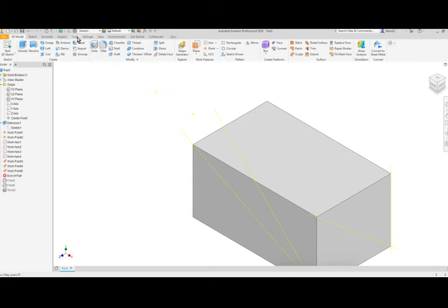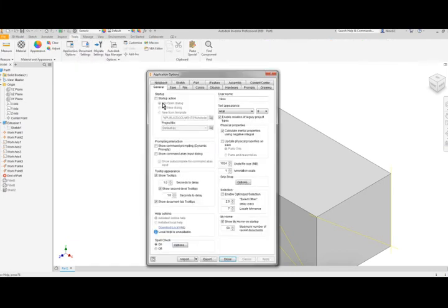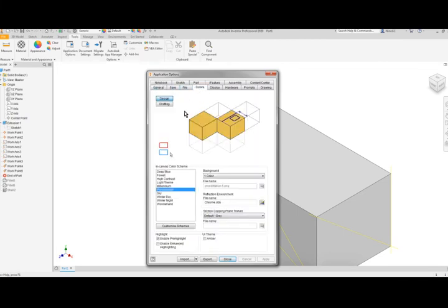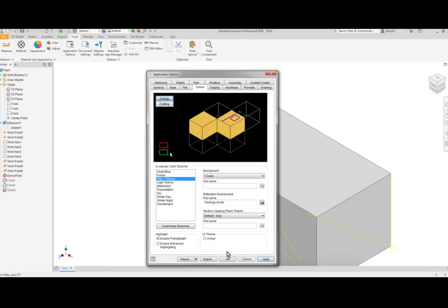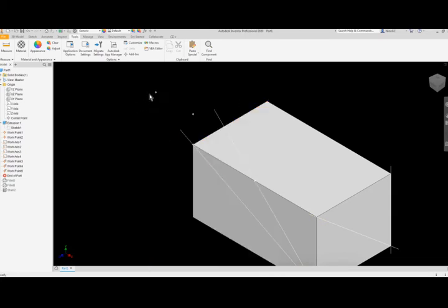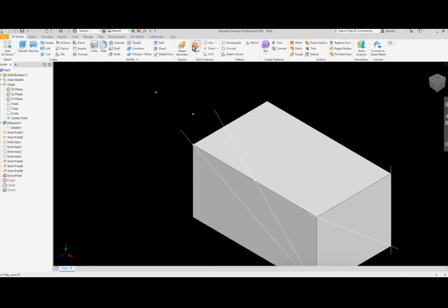I'm just going to go to my tools, and I'm going to change the color of my screen just so that we can see that there are points being created. So I'm going to change the color to high contrast for a second, click Apply, and as you can see, these 2 points have been created off of that. The benefit of doing that is now that I actually have the ability to sketch, because now I can pick, say, 3 points in space. If I can pick 3 points in space, here is the work plane, point 1, point 2, and point 3. I now have a work plane.